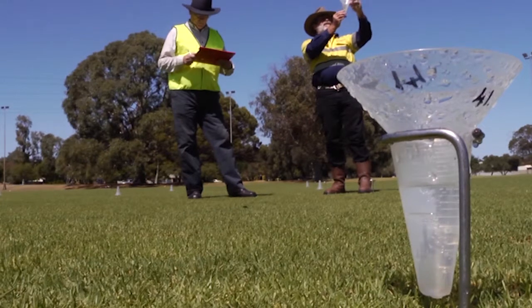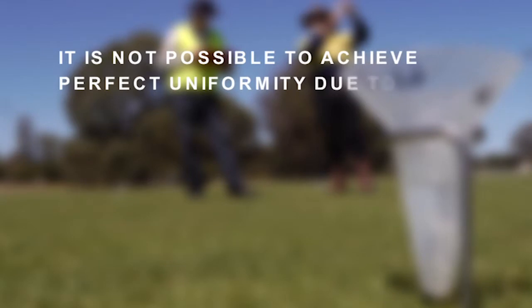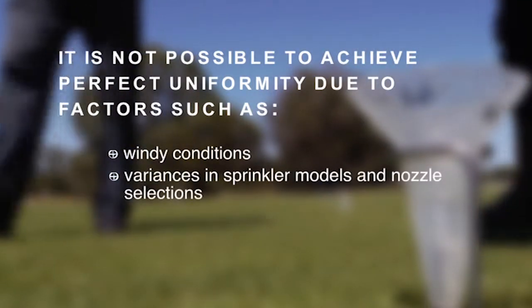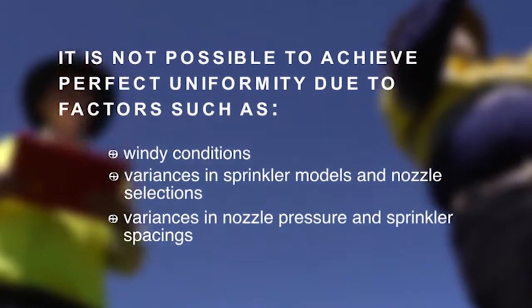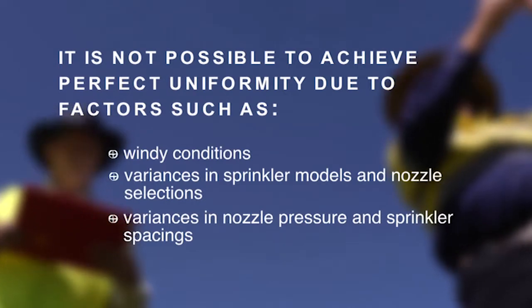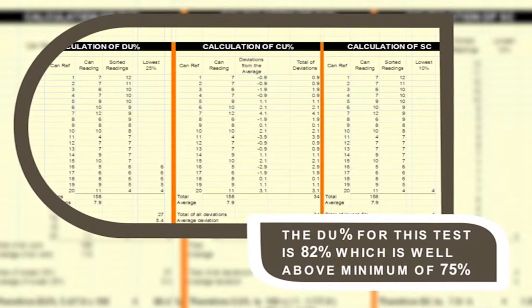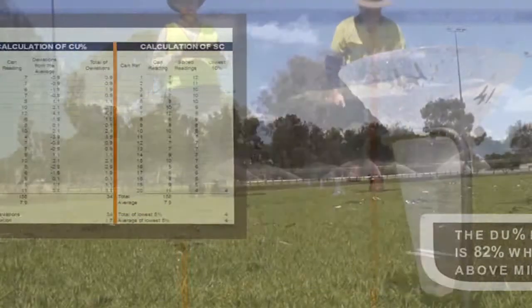In a perfectly uniform system, each of the catch cups would hold the same amount of water after the test. However, it is not possible to achieve perfect uniformity due to a number of factors which may include windy conditions, variances in sprinkler models or nozzle selection, and variances in nozzle pressures and sprinkler spacings can all contribute to lowering uniformity. In the case of this test, the DU percentage is 82%, which is well above the industry accepted minimum of 75%.